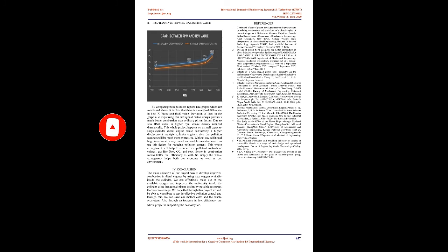Better combustion means better fuel efficiency as well. So simply, the whole arrangement helps both our economy as well as our environment. For conclusion, the main objective of our project was to develop improved combustion in diesel engines by using max oxygen available inside the cylinder. We can effectively make use of the available oxygen and improve the uniformity inside the cylinder using the hexagonal piston design with the resources that we can arrange.